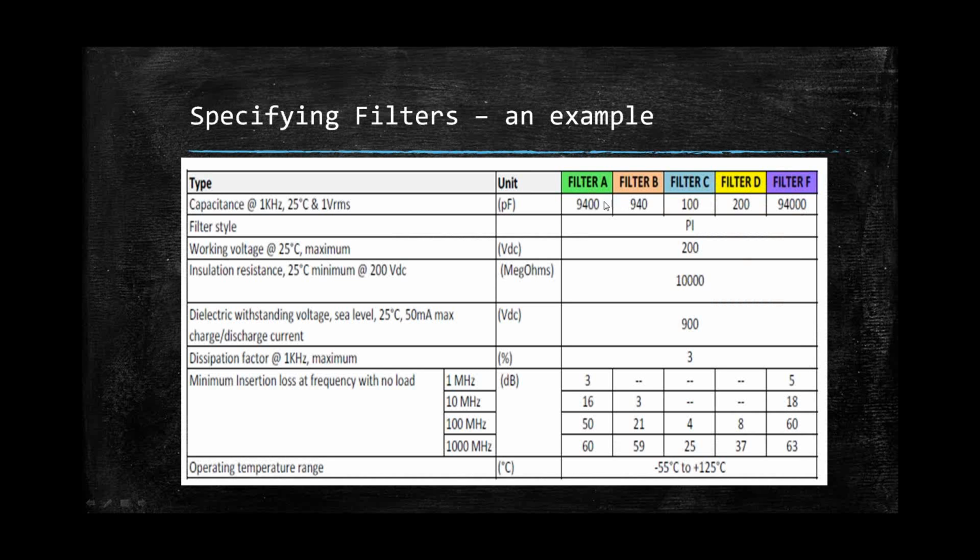If you need that, and that's only at room temperature, if you need something different to go across the minus 55 to plus 125 capacitance level and still hold the plus or minus 20%, then we're going to have to do some work on this to get the proper tolerance range to operate within those temperature ranges. Take a look at your transient voltage requirements as well.